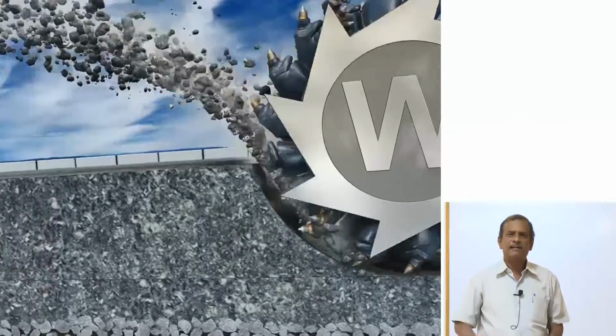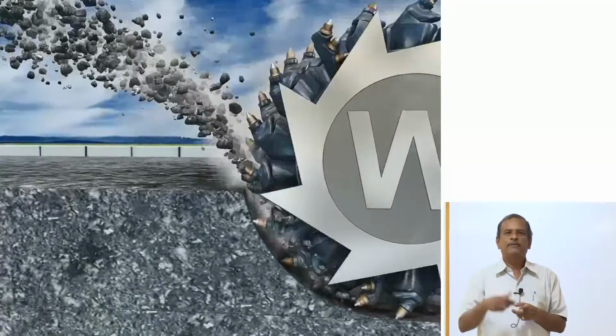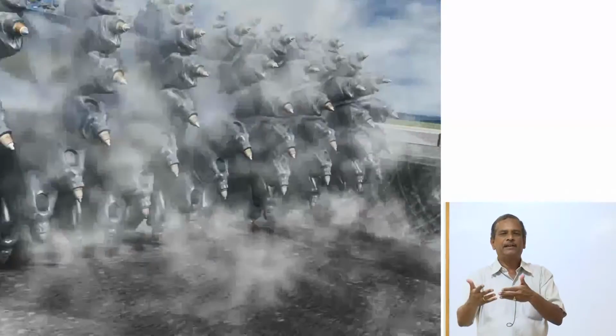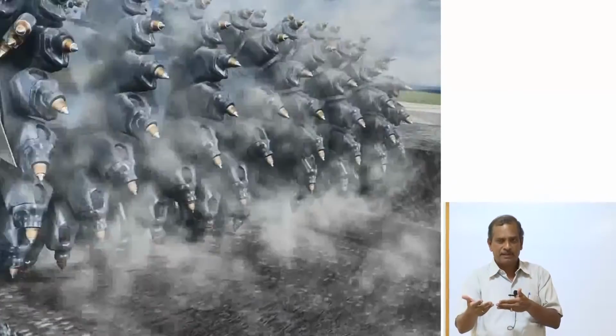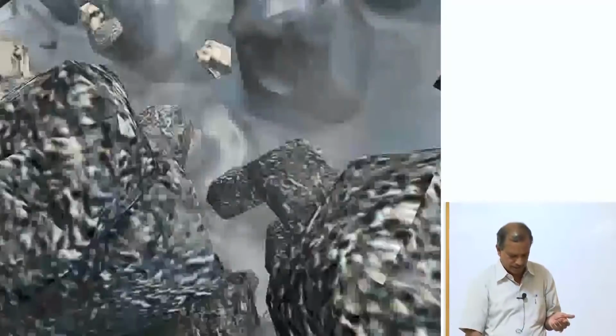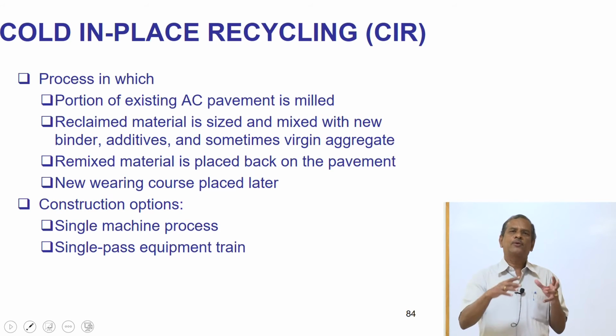So, if you look at this, I can mill the entire material. Now, milling machines are available. If the road has deteriorated, I need not provide an overlay about that. You mill the material, and use the material again and again and again. So, milling is the first step when you want to reuse the materials. Once you mill the material, I can do cold recycling.